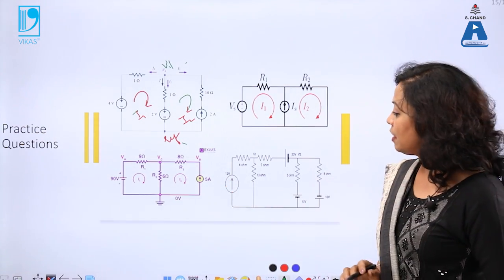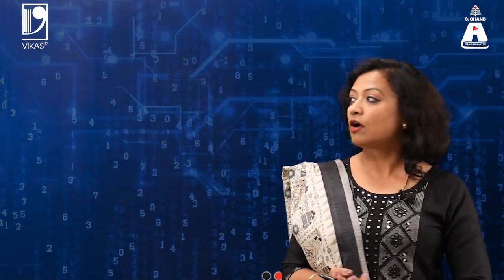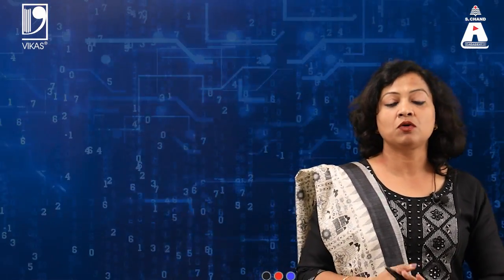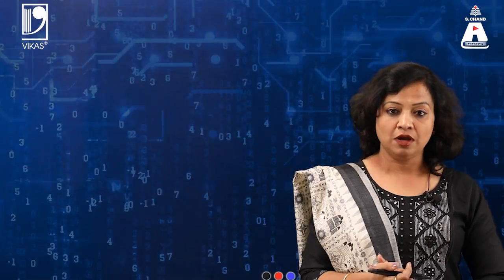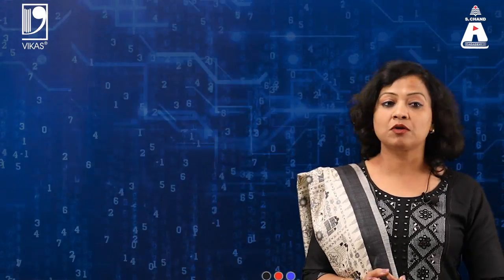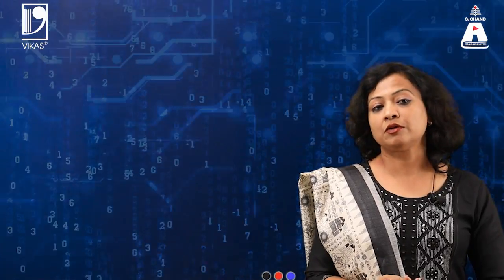So there are a lot of examples with current sources or voltage sources for practice using both analyses. In this video we have discussed mesh analysis, then nodal analysis, using Kirchhoff's law, and the circuit analysis using both techniques. And why do we use mesh and nodal analysis? Because for a complicated circuit it is very difficult to find total resistance, total current, then the current division rule. If there are n number of branches, it can be 100 or 200 branches. So using mesh or nodal analysis, the circuit analysis becomes slightly easy because the number of equations reduces in that case.